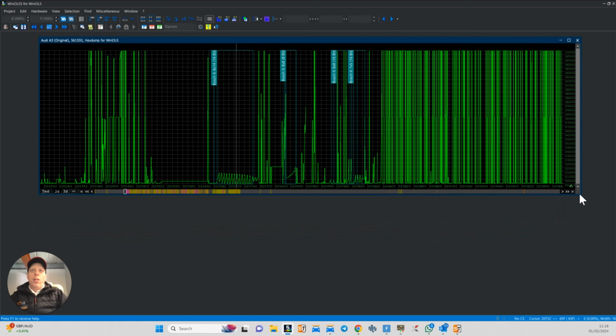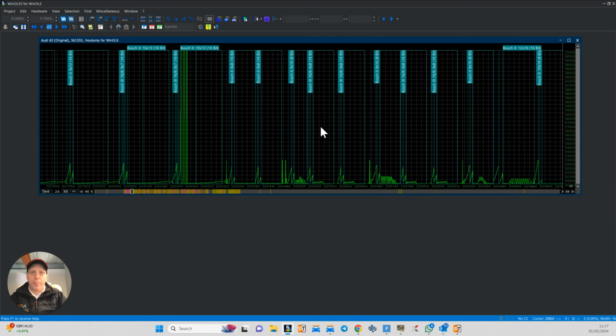Now, I always say, if you're coming into a new ECU on a development basis, then log the car. Log it, because you need to understand exactly what that car is doing. So what torque are you requesting, what boost are you requesting, what injection timing are you seeing, and all these things to try and make sense of the map itself. So you can start painting a picture of what's going on with the ECU.